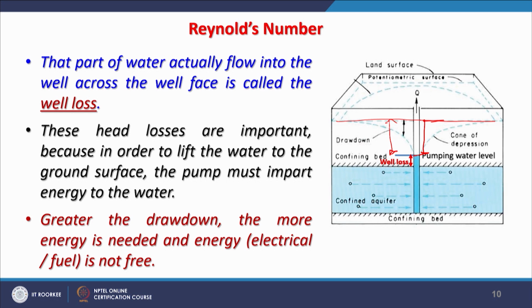So, that is why it is better to switch off the pump for some time, depending on the geological conditions. One can estimate all these things, so that one would know how much time it would take for things to settle. That means the drawdown should disappear or the cone disappears, say in 2 hours, 5 hours, or maybe overnight. So, generally it is done.